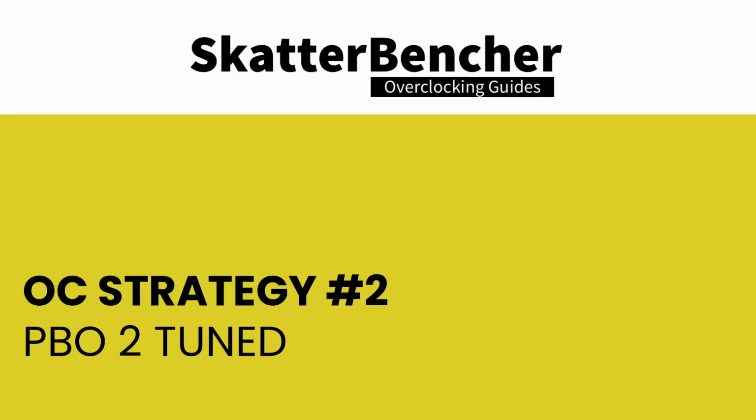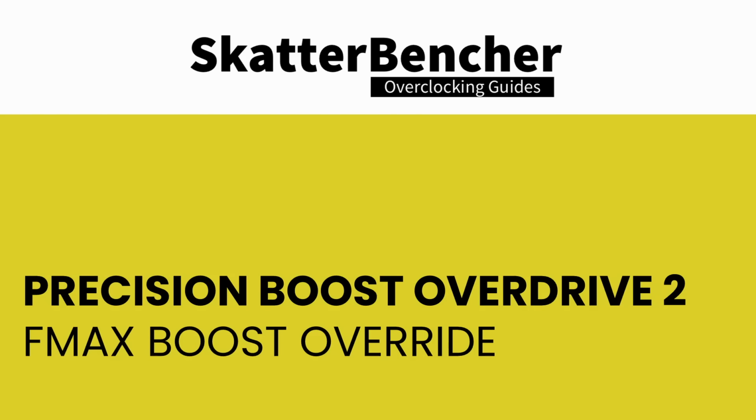In our second overclocking strategy, we tune the CPU's Precision Boost 2 boosting algorithm by using some of the tools available in the Precision Boost Overdrive 2 toolkit. Fused maximum frequency, or Fmax, is one of the Precision Boost infrastructure limiters managing the CPU performance. Essentially, Fmax determines the maximum allowed operating frequency for each of the 8 cores in our Ryzen 7 9800X3D.